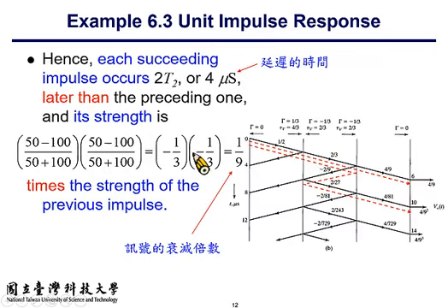Okay, so how about the other side? The first term that comes back to the source side will be the reflection at the 1-2 interface. All right, so what is the propagation delay needed? 4 microseconds, right? How about this one? You can trace the path, that will be 8 microseconds. How about the third one? That will be another 4 microseconds, so it's 12 microseconds.